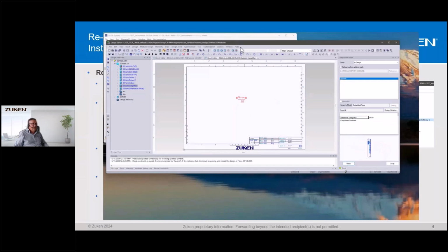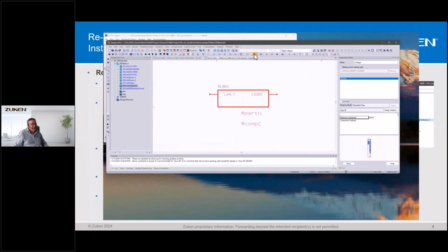So what we need in the next step is getting sheet connectors to the left and the right hand side, and of course also connecting and labeling those sheet connectors to the circuitry. This is what's going to be happening now. So once we got the labels, we now go with a double click into that design.